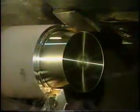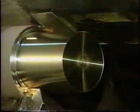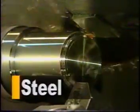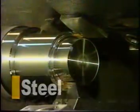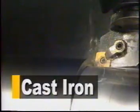The type of material being machined determines the grade of carbide to be used. Different workpiece materials produce different types of chips. Flowing continuous chips are produced by steel. Segmented broken chips are produced by cast iron.